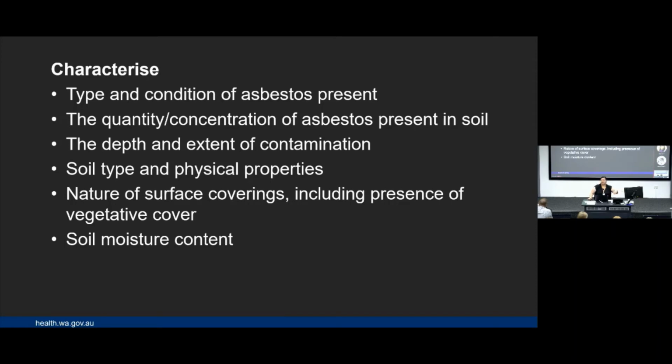You can test pit using a sampling density that's in the table in the guidelines and say, hey, is there actually contamination in these soils? And you can do surface scrapes as your test pit rather than very deep scrapes, depending on what you define as your soil contamination layer, if that makes sense.